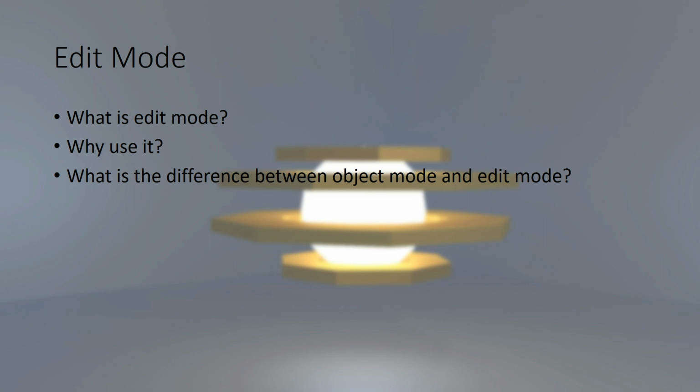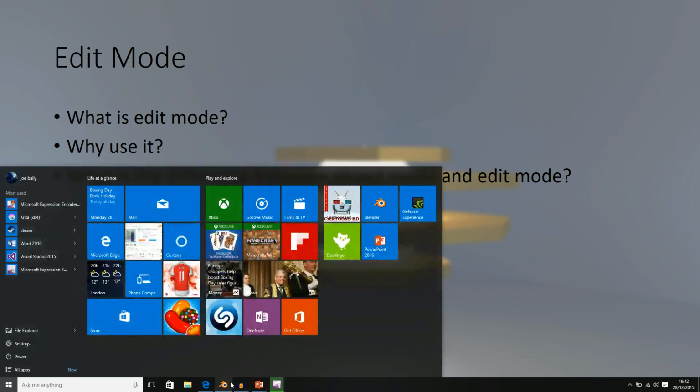Edit mode is where we create and delete parts of an object and we remodify that object. So that's the main difference. The main difference is in object mode you focus on the core aspects of location, rotation and scale, and edit mode is all about the finer details. A couple more differences between the two. First of all, in edit mode you can only edit and select parts of the mesh or object that was selected. So I'll give you a quick example of that in Blender.